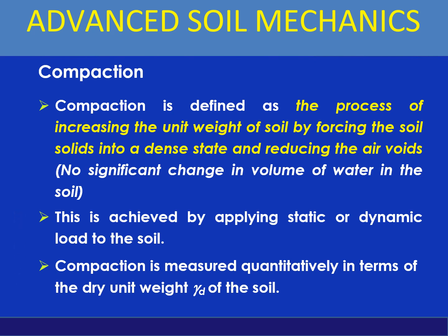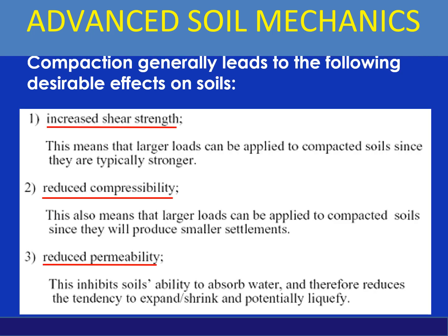Compaction is measured quantitatively in terms of the dry unit weight, that is gamma sub d of the soil. So compaction generally leads to the following desirable effects on soils: increased shear strength, reduced compressibility, and reduced permeability.